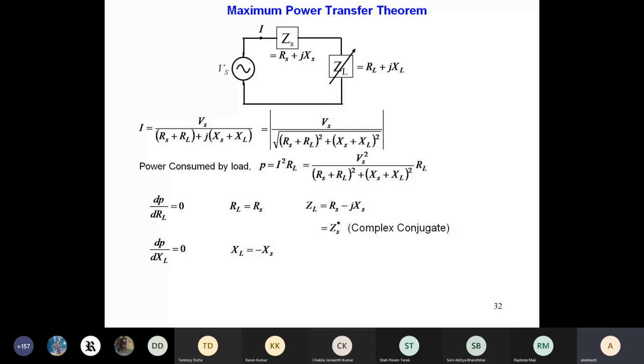So this is the maximum power transfer theorem, a very important theorem, just like your DC, and you will get numericals related to that. The only difference you have to remember, and this derivation you should do on your own, which I have not shown here, is the equating to 0 and getting this condition. It is a simple derivation and should not lead to any complex expressions. So the maximum power is derived in case of AC when the load impedance is the complex conjugate of the source impedance. You can write down the statement, or you get the statements in the books.